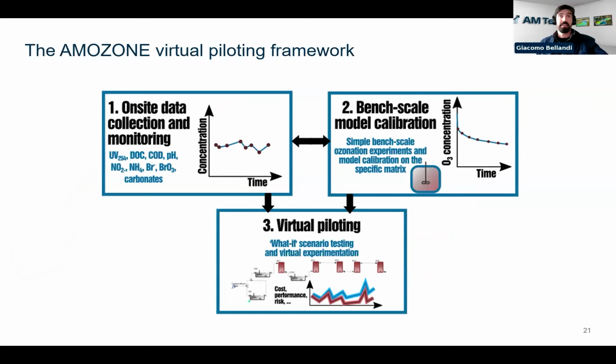We applied the virtual piloting framework, which is about collecting on-site data and using the water that is going to be treated to run batch calibration tests, with which we calibrated the kinetic model, and with which calibration you can run a virtual pilot. So you can scale up from your batch test in the lab to a full pilot installation.